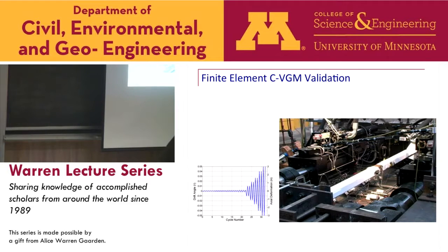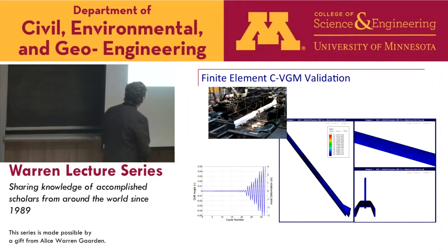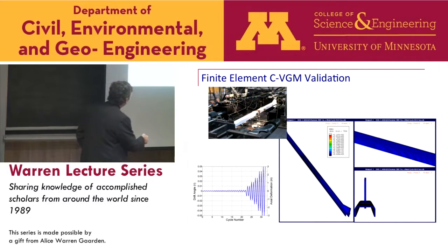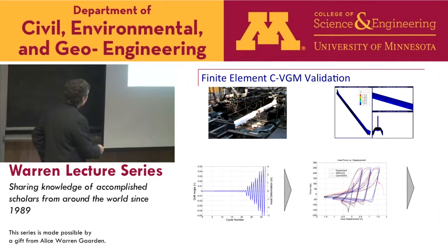Then our goal was to make finite element models of those and see if we could simulate that behavior at a global scale. These are continuum brick finite elements, several through the thickness, where we model the overall brace, applying the same loading protocol. And this is a zoomed-in picture of what's happening at the middle of that brace. You can see we pick up the local buckling and then the concentration of stresses and strains in that upper corner. And this is a comparison of the overall load-deformation response, which was picked up remarkably well.